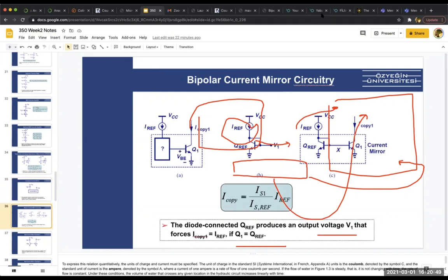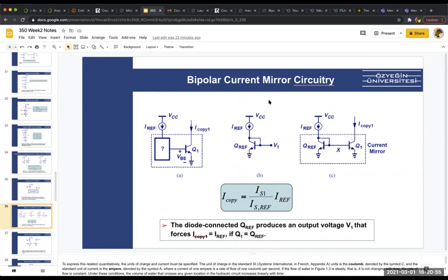So now we will show how we design those current mirrors, how we can create these different versions. While we are discussing how we can duplicate it, we are also looking at the ways that produce minimum change. Because let's say our IREF, golden current source, is 1 milliamp. If you want to double it, make it 2 milliamp, we don't really want it to be 2.1 either, right? We want to double it perfectly.